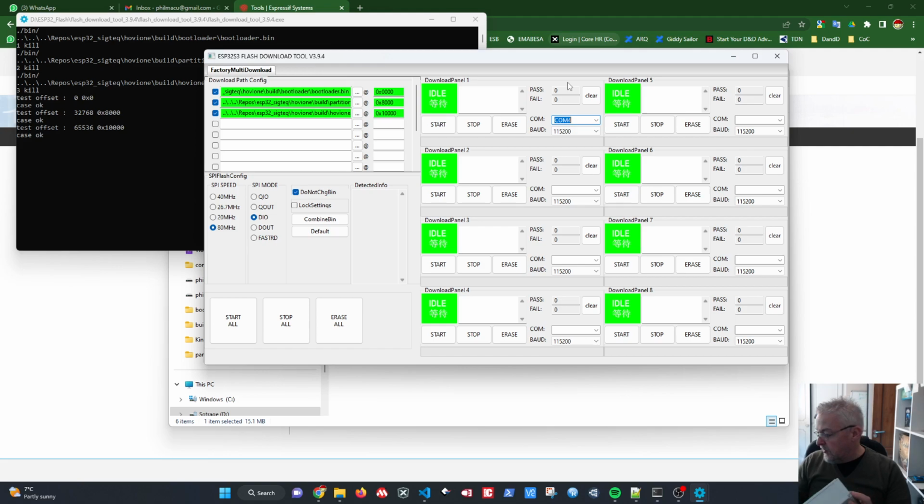Although it's very handy if you want to keep a build folder of your binaries that are out in the field, and you want to be just able to flash them up on a laptop or on a device that you don't have to install Visual Studio Code and have all the updates and have everything. You just can create your binaries. And what I do is I create my binaries on this machine, and then through Google Drive, I upload those 3 files and a notepad file saying, hey, the settings for this micro are such and such. Here's the 3 binaries, and I put that up on my Google Drive.